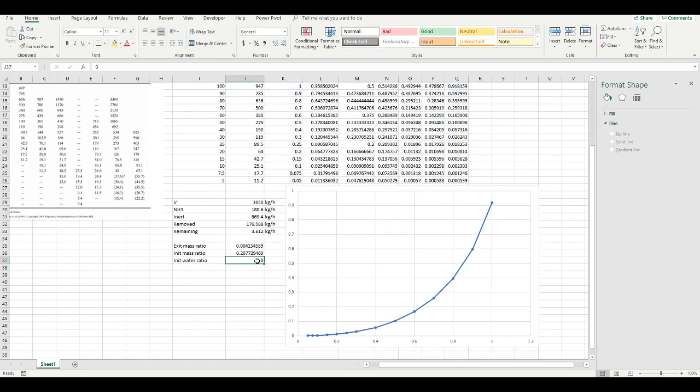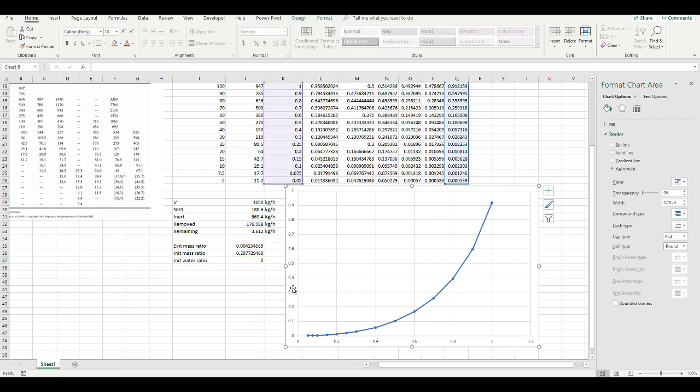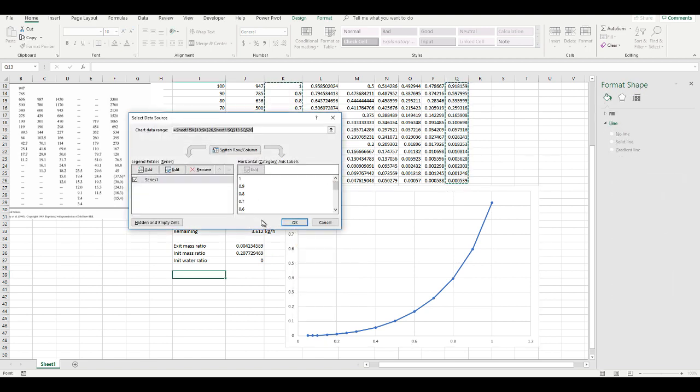So to do that, Lmin is found from the slope of our operating line. So what is our operating line going to look like in a minimum flow situation? Well, it's going to pinch the equilibrium line at some point. So before we start tracing the line, we know that it has to pass through a specific point. So it has to pass through the concentration of the vapor and liquid streams at the bottom of the column.